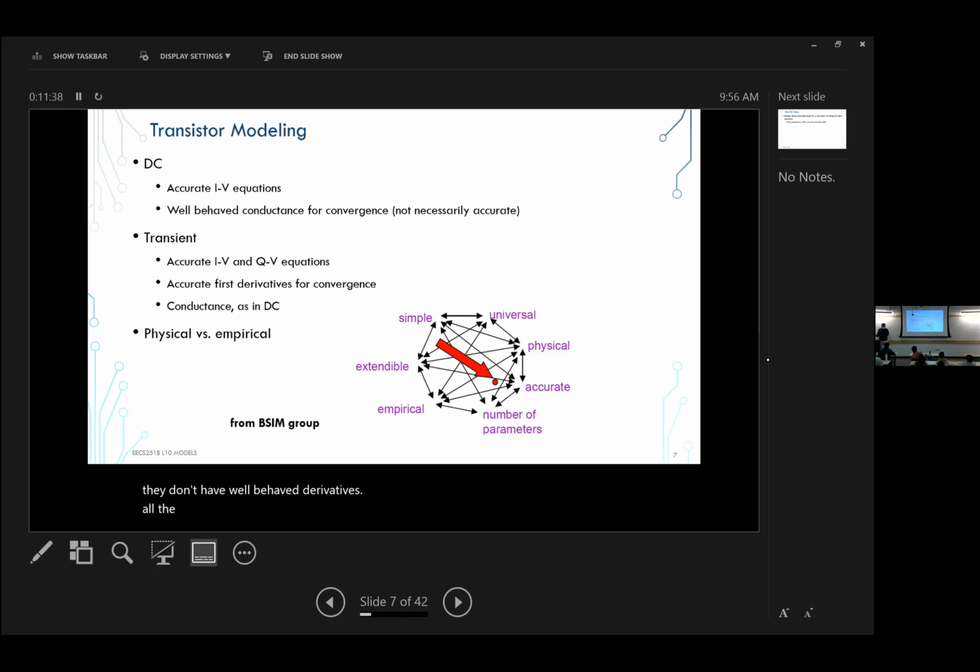In general, we're spoiled now. When I was a student, these convergence issues were all over the place. Can't find the DC point, sorry. I cannot find the operating point, sorry, try again. And then there are all these fudgings that you do to the network, to your SPICE netlist, to help it find the operating point. But these models have been built to do that.